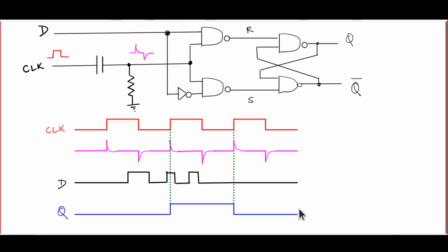One important point though, in an actual practical circuit, you do not really use a CR to shape the clock pulse into these spikes. The reason you don't is rather simple. It's just economics. To create a capacitor on an integrated chip requires a large area. And in that area, you could have fit in perhaps thousands of transistors.